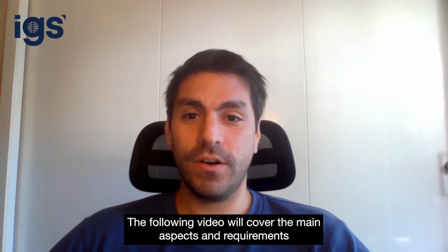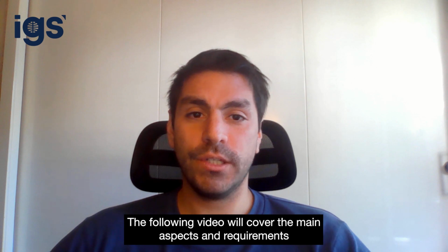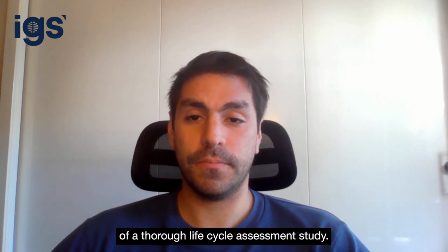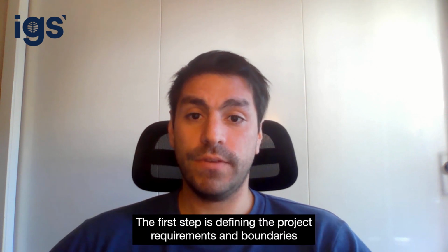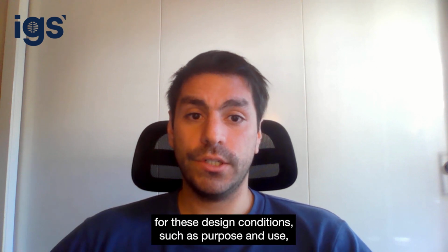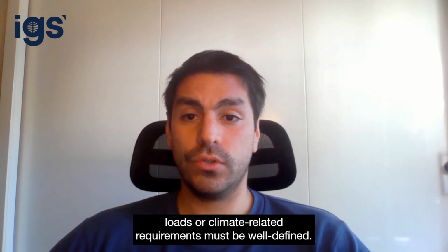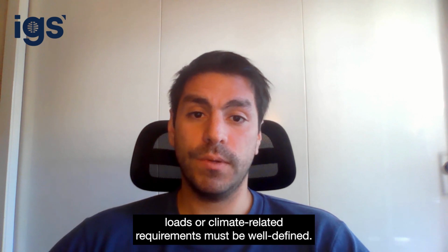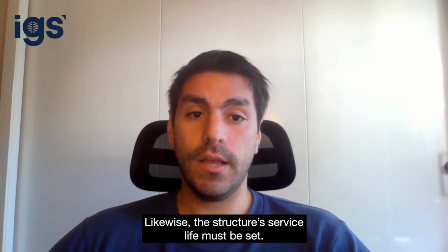Welcome. The following video will cover the main aspects and requirements of a thorough life cycle assessment study. The first step is defining the project requirements and boundaries. For this, design conditions such as purpose and use, loads, or climate-related requirements must be well defined. Likewise, the structure service life must be set.